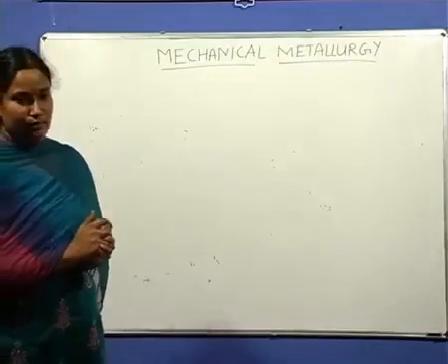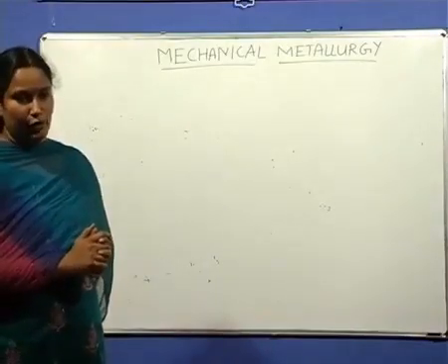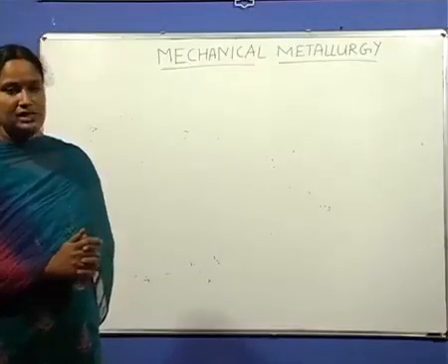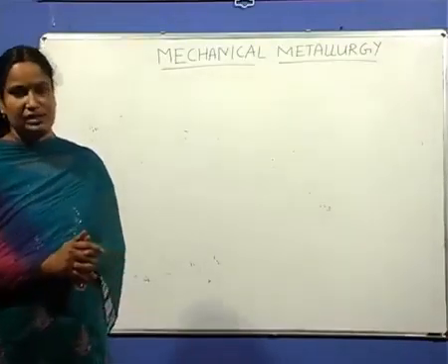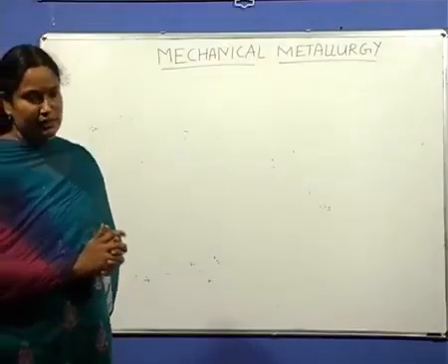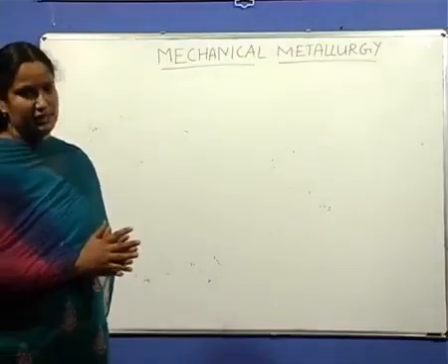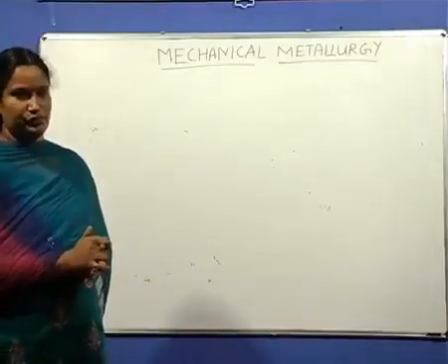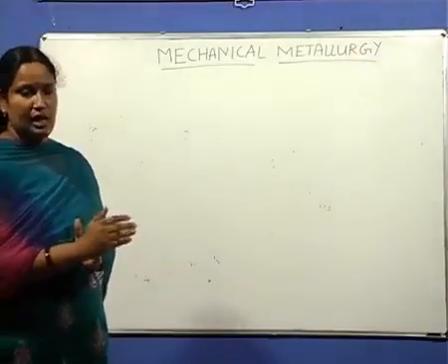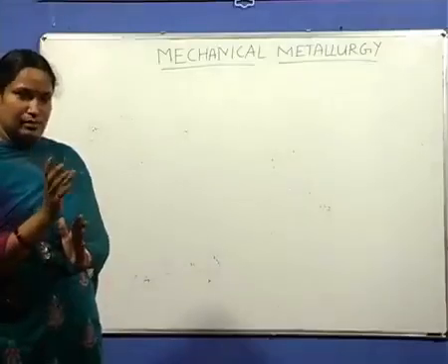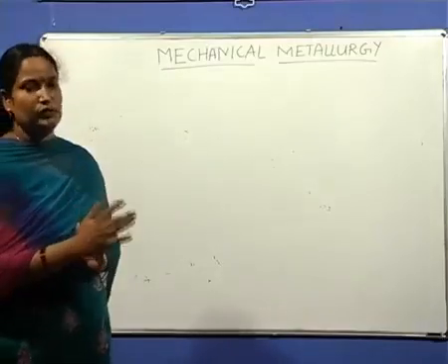In the case of time independent, examples are elastomers, that is rubbers, which show a non-linear elastic behavior. Another example of non-linear elasticity is viscoelastic materials, which are seen in most polymeric materials as well as some polycrystalline materials to a lesser extent over a certain temperature range. The loading and unloading paths do not follow the same path, and there is some time dependent strain. That means the strain recovers after the removal of load with respect to time.